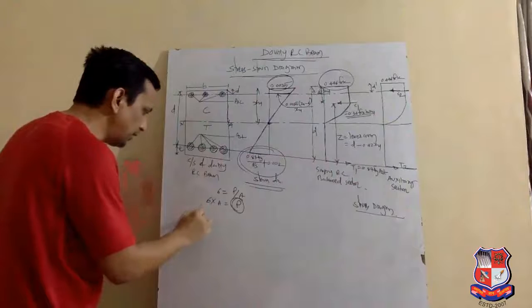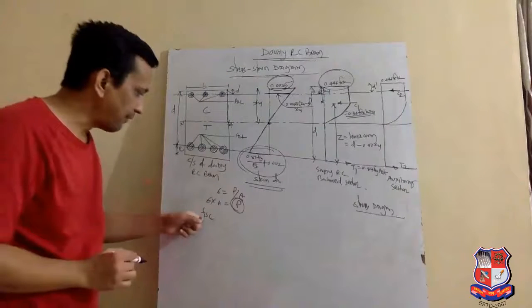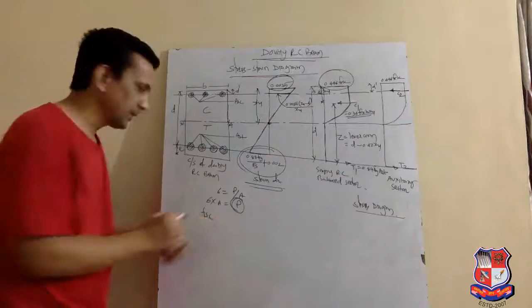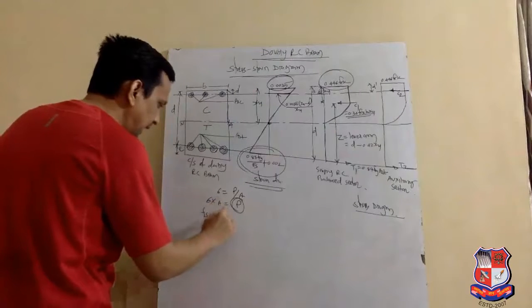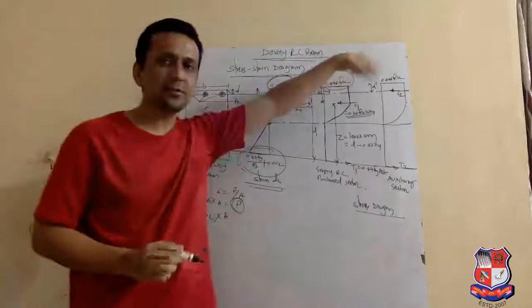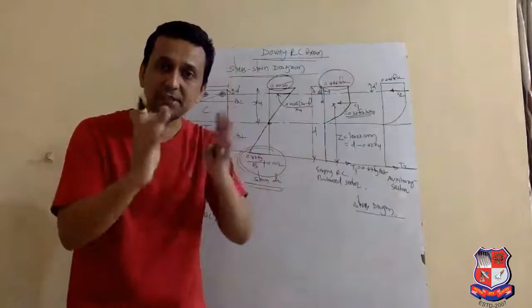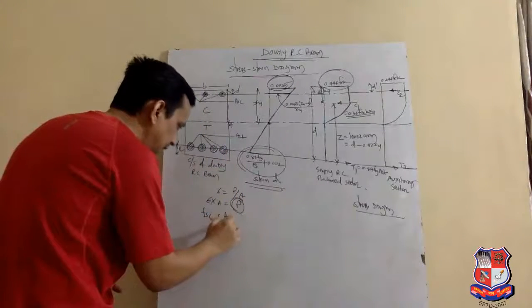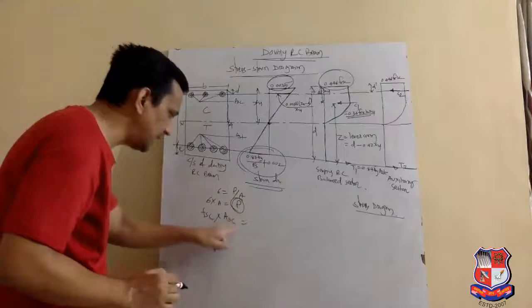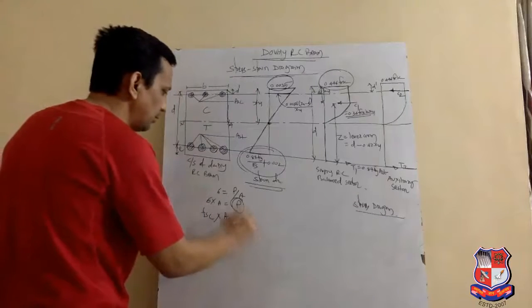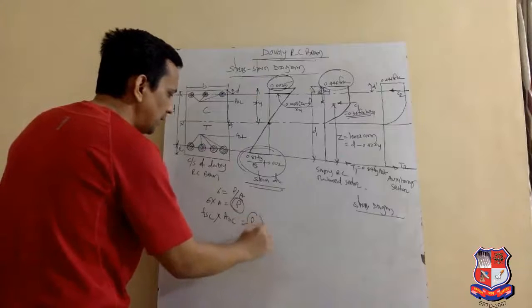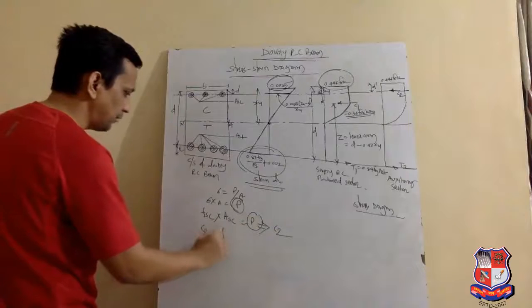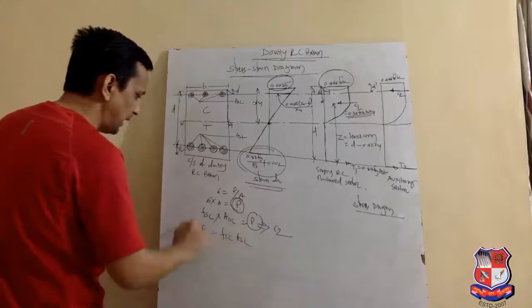It is denoted as fsc, the stress in steel in the compression zone, into the area. This compressive force is due to the compression reinforcement that we have provided in the compression zone. It means the area Asc, the area of steel in compression, is equal to P, and we denote P as C2. So the equation of C2 comes to fsc into Asc.